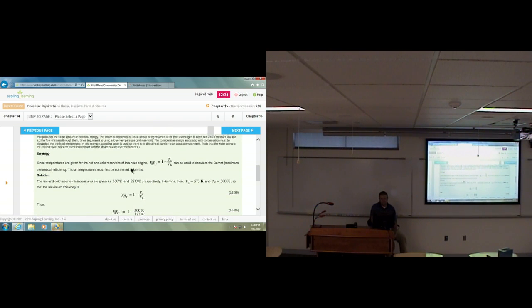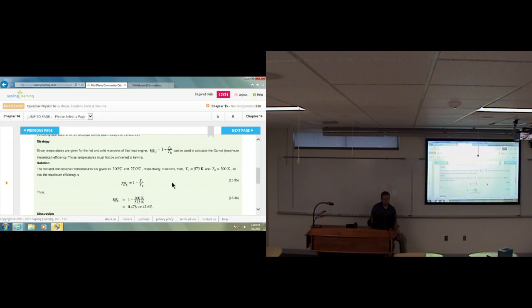So what is the efficiency? If we consider this to be a Carnot engine, for example, if this had the maximum efficiency, the most efficient it could be, it would be a Carnot engine. And we're using water, so the coldest the water is going to be able to get, it turns out, is 27 degrees Celsius. If it gets much colder than that, you start dealing with other problems. You don't want icing, for example, in your water, so you have to keep it at a reasonable temperature. Also, you don't want to have to cool it using a refrigerator, because then you're detracting efficiency.